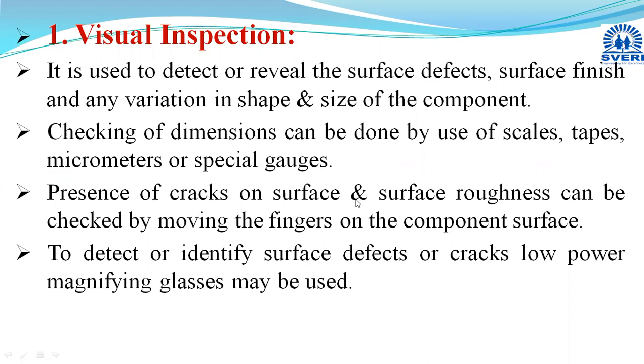The presence of surface cracks and the quality of the surface finish, whether it is rough or fine, can be checked by moving the fingers on the component. If it is a rough surface, we can feel that with the help of our fingers, or if it is fine, we can determine that also. And if any kind of crack is there on the surface, that also can be identified.